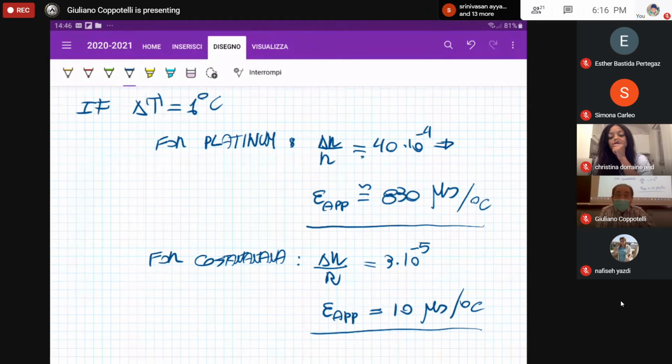That is a very large difference, because we are interested in measuring about tens, hundreds of microstrain. So 800 means a lot of difference, just because of 1 degree. If you are using that with a 10 degrees difference, then there is a very large amount of error.